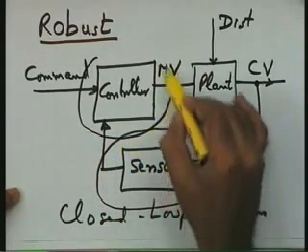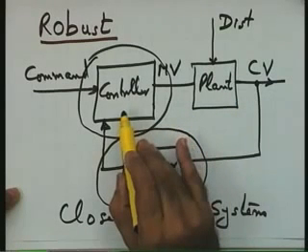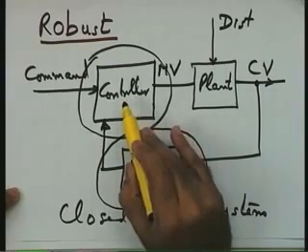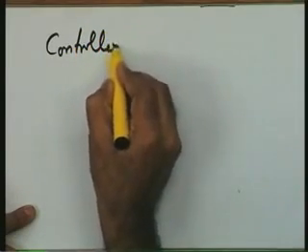One approach could be the experimental approach. In this approach, what I do is install a controller based on practical experience on the process of the plant. There are certain parameters of this controller which I can then adjust online, so that the controlled variable follows the command to an accuracy acceptable to the process engineer, acceptable to the user. This particular experimental design in the literature is referred to as controller tuning.